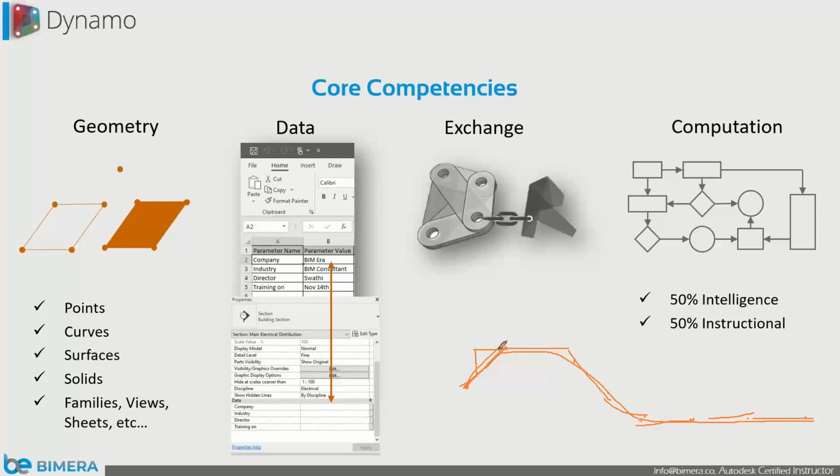It means you already have a curve, and you will be converting that into points, and you will take an offset from the wall here. From the wall, let's consider it's 100 mm. Okay, 100 mm, and you will start placing the ducts like this. And again, you will be maintaining some 150 mm space. Then you will draw one cable tray next to it. So how do you play with all this stuff? You have to understand the directions, to place the planes, to get the vectors. So there is additional stuff.